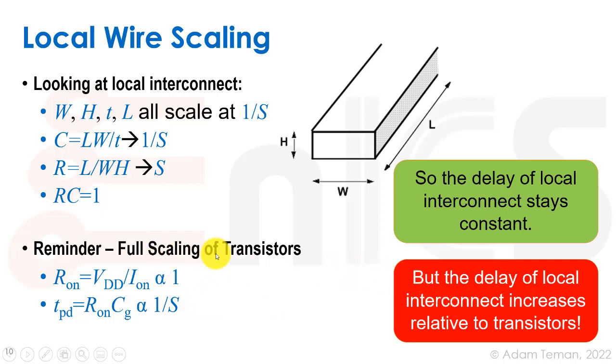And especially if we didn't use full scaling of transistors, which we didn't do for many years, but rather we were getting better speeds than the interconnect, which was a non-factor in older process technologies, at some point became the same order of magnitude, and possibly in some cases even overtakes the delay of the transistors themselves, and that's a real bad thing. And therefore we had to go to other things like not scaling the height, changing the materials, and so forth.